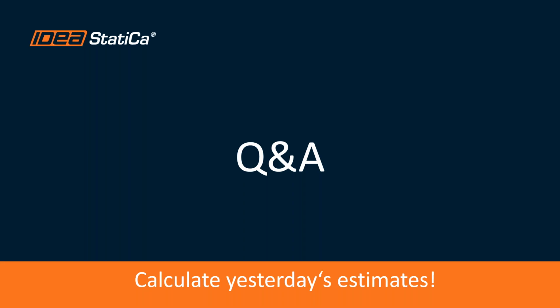So you can keep on your machine versions, for example, 20 and then 20.1, and it's the same with 21.0 and 21.1. So you can keep all of them, but of course keep in mind that once you open, for example, your project or create your project in version 21, you will not be able to open it in version 20. So you cannot open that in older versions.